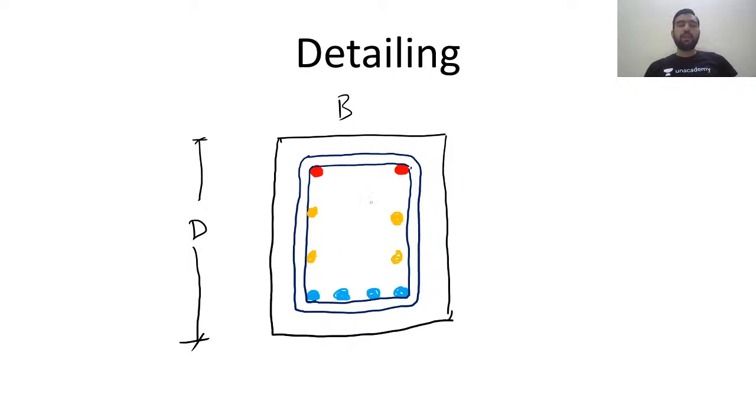You can see here it is actually decreasing the effective length, or you can say spacing between two extreme steel bars. So due to this the effective length of this bar is reduced, and the intactness of the cage is also going to increase. So guys, the bar which I have shown you is your side face reinforcement.